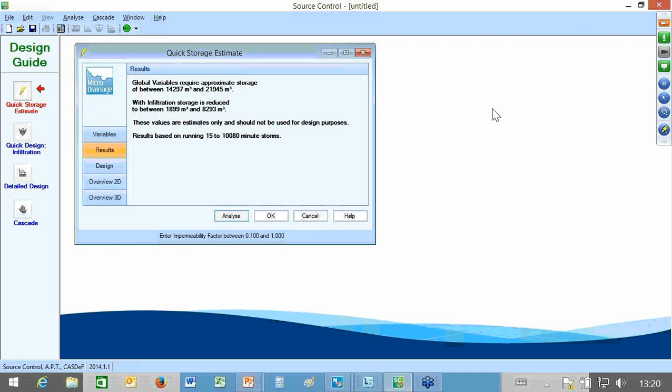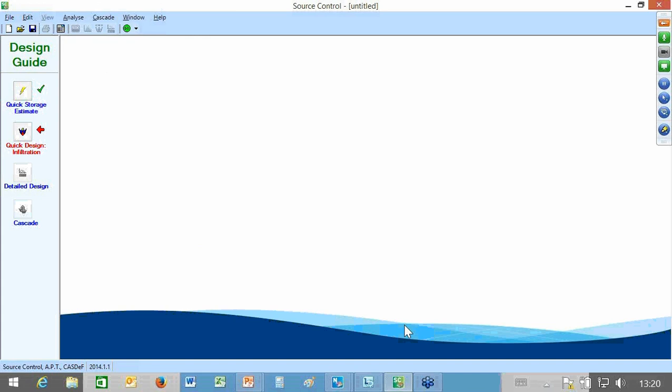So this is again guidance, BRE Digest 365. These structures must half drain down in time for the next event, within 24 hours basically. So there's a half drain down time criteria. We'll see this when I say OK. So we can set up back-to-back designs, and we could set up a rainfall profile to run one straight after the other if we wanted to.